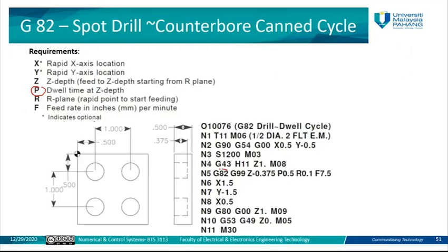As you can see here, this is the part which is involved in the G code for the drilling, and all the previous lines are either to make some comments, to define the program, the type of program, what type of coordinates, and what the speed is. Then we go for the length compensation and offset of the drill, then the depth or the standby position. Then we start to talk about the other parameters, which are more related to the drilling process.